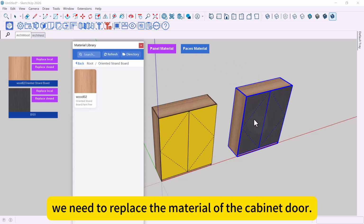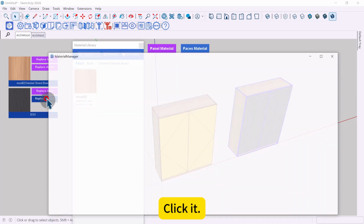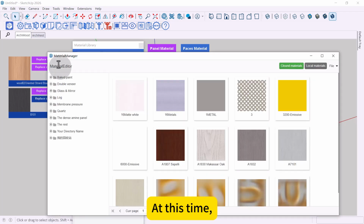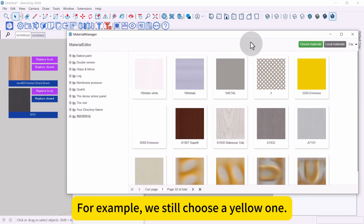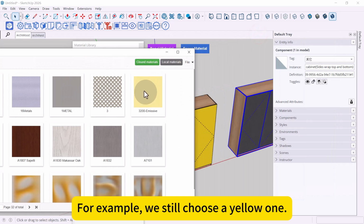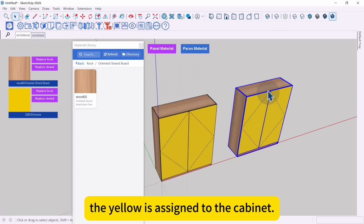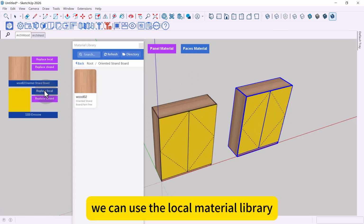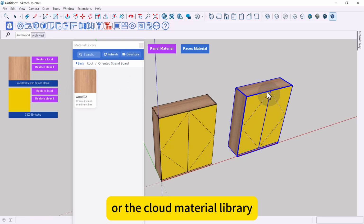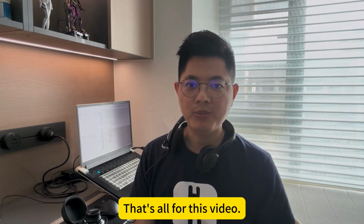Okay. Next, we need to replace the material of the cabinet door. We can use cloud materials. Click it. At this time, the cloud material library panel will be displayed. For example, we still choose a yellow one. Click on yellow. At this time, we can see that the yellow is assigned to the cabinet. In this way, we can use the local material library or the cloud material library to assign materials to our model. Okay, that's all for this video.